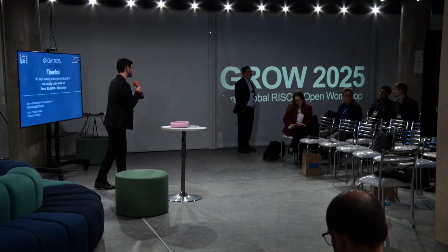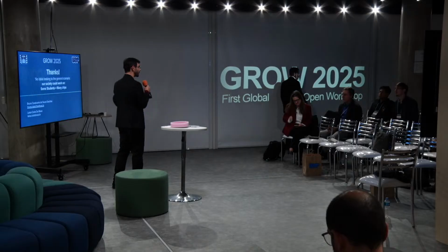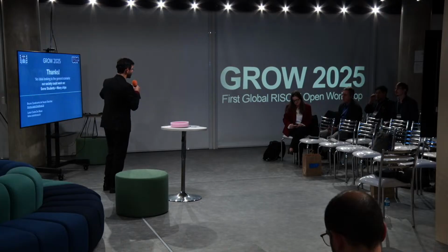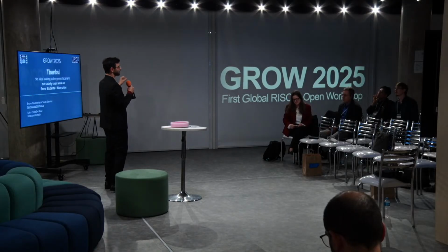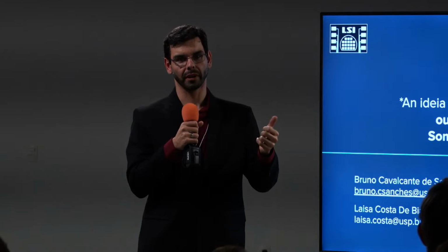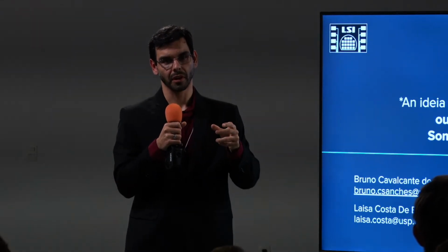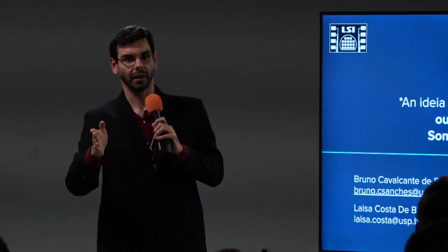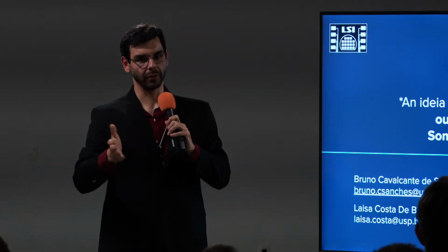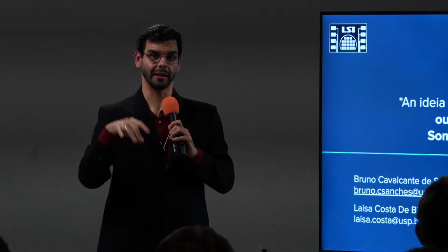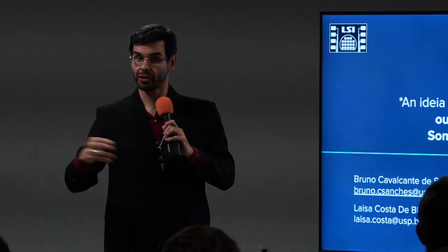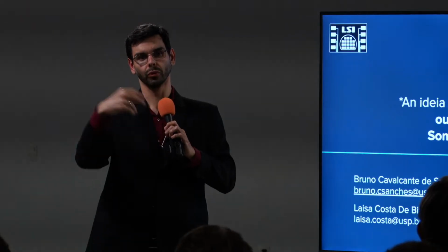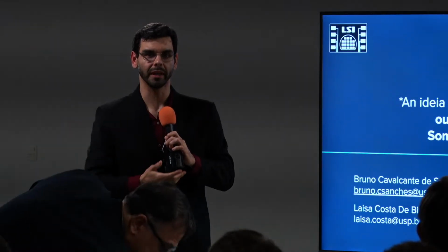Yes, the first step the team was making was trying to get the chips for the Pulga one, the small one. This we more or less are achieving. So we got the RISC-V core, 2 versions of it, it's working, and we got the power management. But now one path we can go is to try to do it in open PDK and open tools, because right now they were designed in UMC 65, which is not an open PDK right now. So we should investigate doing it with one open PDK.